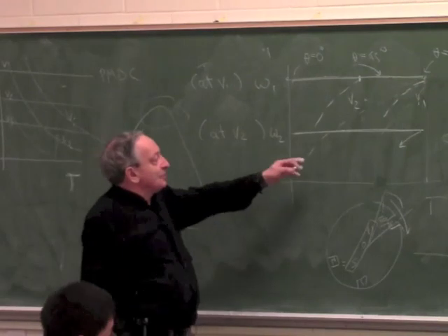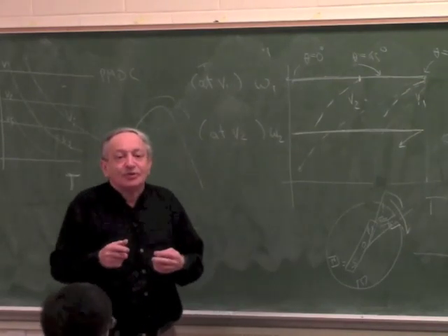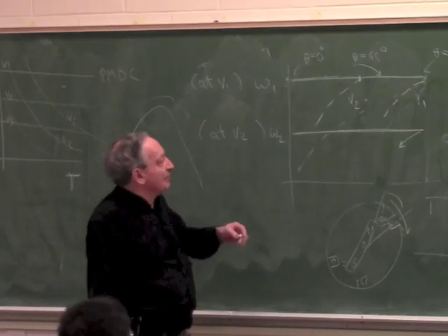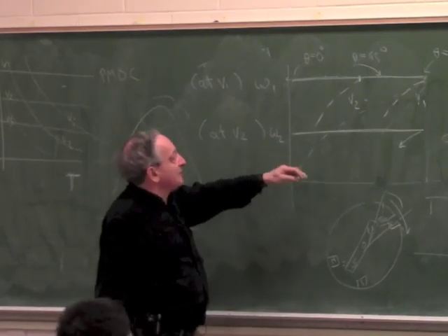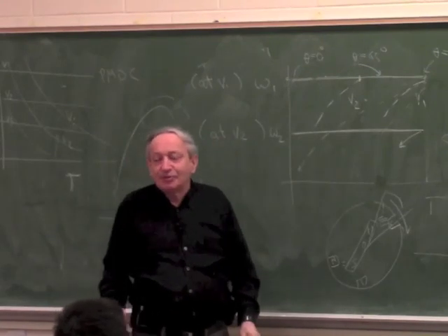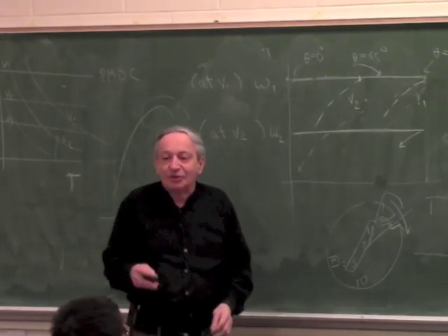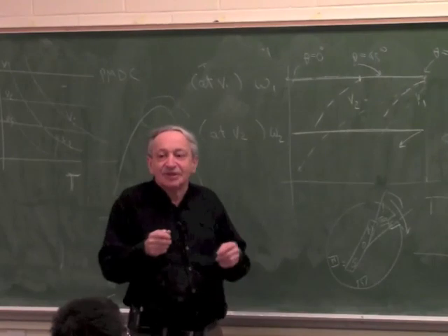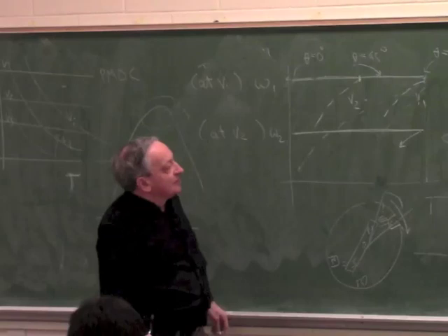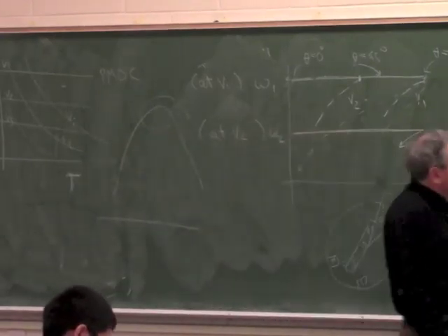Now, in this motor, no matter what you want to do, you have to adjust 2 parameters. Okay, so if you want a new operating point, unless the operating point is the same speed, okay, if you want a different operating point, meaning different speed, different torque, you have to always adjust 2 parameters, the frequency and the voltage. Clear? Good. Okay.